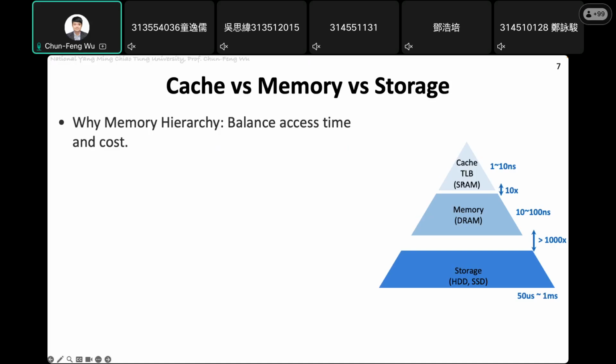Because usually SRAM is quite expensive, and also the area cost for SRAM is super high. So usually the size of the SRAM is a couple of megabytes, right? If you look at the CPU, with an embedded CPU, the SRAM will usually be something like 32 or several hundred kilobytes. And if you have a PC, then usually the SRAM size is maybe 10 megabytes or tens of megabytes later. So it's quite small compared with the host DRAM.